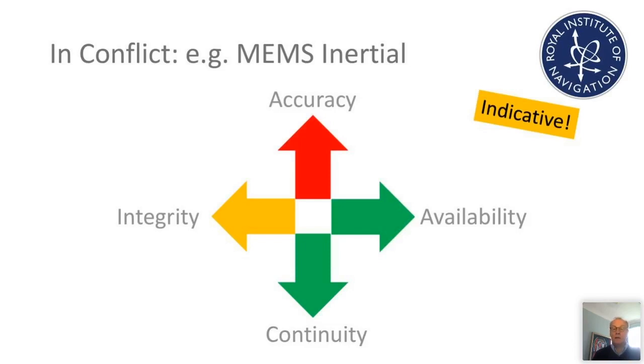So it's on all the time, very difficult to spoof or jam, but very high drift in accuracy. So while it might be fairly accurate initially, it's open loop cumulative, and Terry will talk more about this next Wednesday. So very poor accuracy. Integrity, well, yes, it doesn't necessarily tell you whether what you're reading is good or bad, so not great.